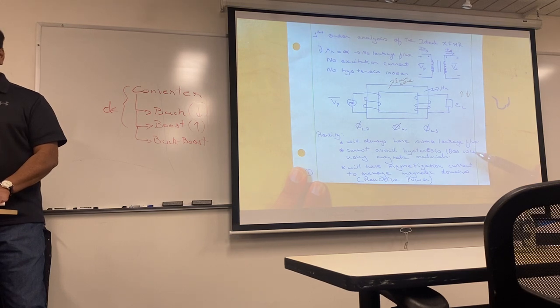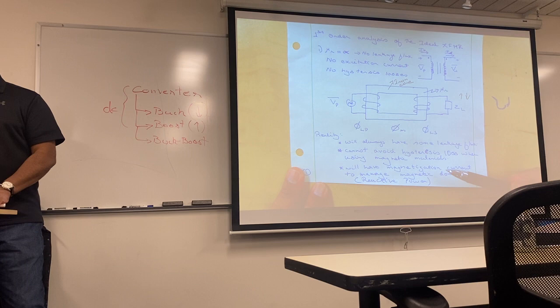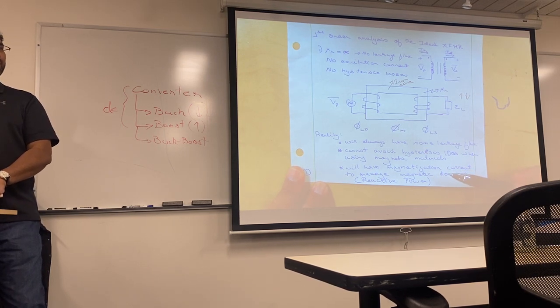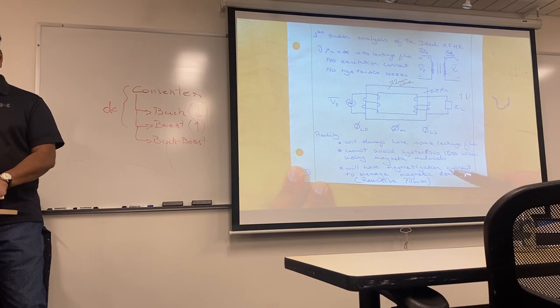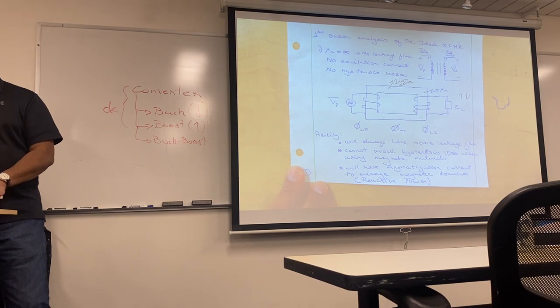And second, when you have a ferromagnetic substance, it is going to go through something called hysteresis. And the last is, have you guys learned about magnetic domains in any of your classes? Okay. You will always have a magnetization current no matter what, and that's to manage your magnetic domains.